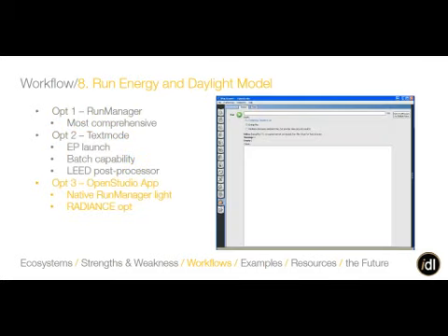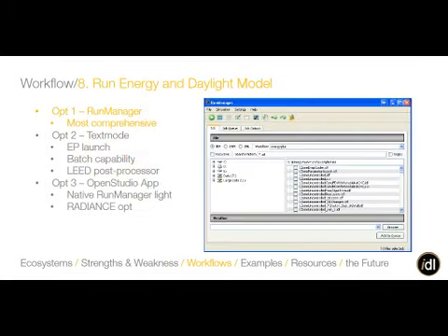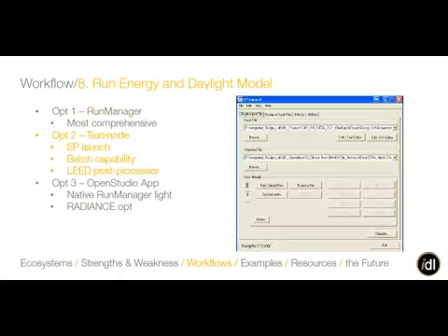Great question. So when we're running the EnergyPlus and daylight model, depending upon which program you're using, there are 3 different options. One is just a separate application. It's called the Run Manager. It can run IDFs that have been created in Textmode, or it can run OSMs that were created in OpenStudio. It's the most comprehensive. We never use it. We're only using option 2 or option 3.